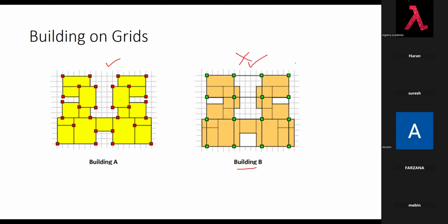But this kind of building is highly recommended for seismic effect, because it will not give you additional torsion due to seismic. Because of this asymmetry, let's say my earthquake is happening in the x direction, this building will move along this axis only. Let's assume all other stiffness and masses are the same.